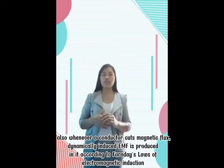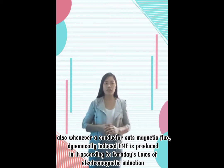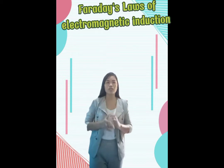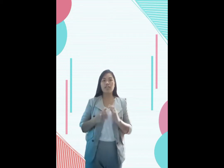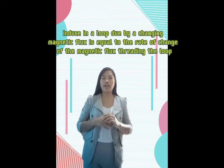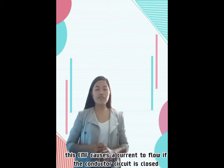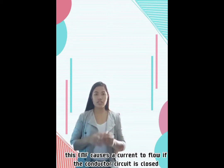Also, whenever a conductor cuts magnetic flux, dynamically induced EMF or electromotive force is produced in it according to Faraday's law of electromagnetic induction. So what is Faraday's law of electromagnetic induction? In short, the EMF induced in a loop due to a changing magnetic flux is equal to the rate of change of the magnetic flux linking the loop. This EMF also causes a current to flow if the conductor is in a closed circuit.